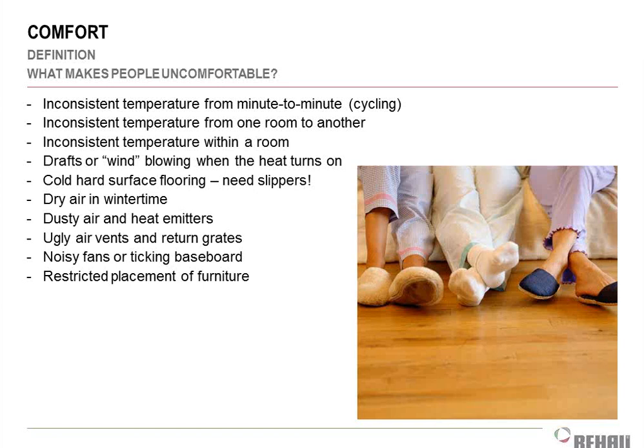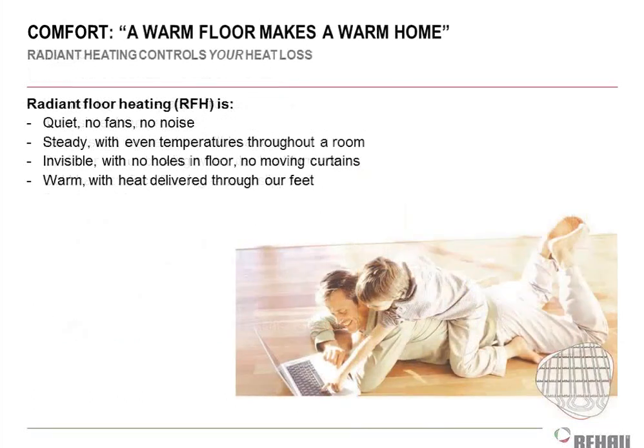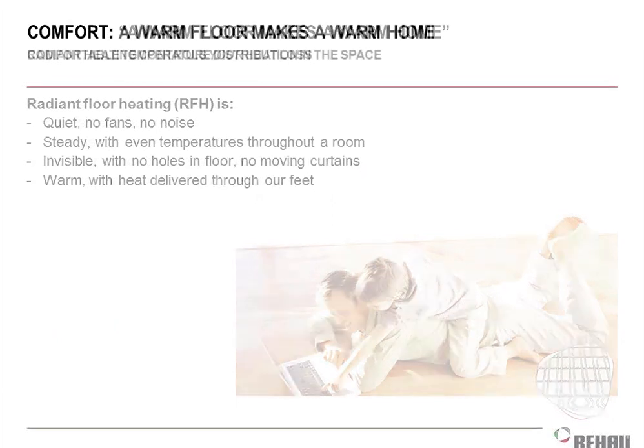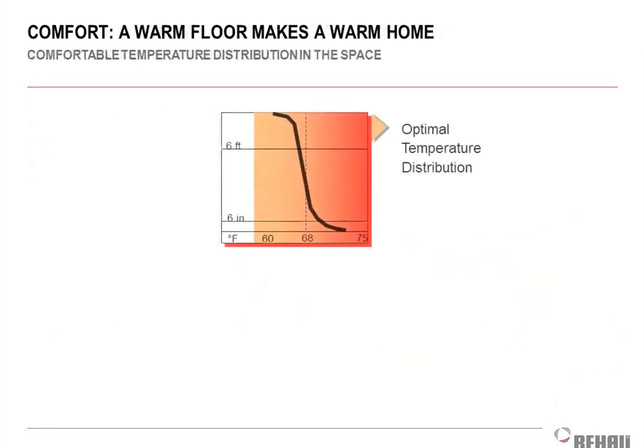And you have more flexibility with how you move things, desks and furniture around the office space or at home, couches and things like that, because the whole floor is a giant radiator to you, right? So that's one of the goals of these radiant systems. We can get rid of some of the sound noise issues. We can keep the temperature significantly more even than we can with any air-based type system, and it actually is warmer when you're walking on it. So a lot of you probably know about ASHRAE Standard 55, which is the thermal comfort standard that we follow as a country.